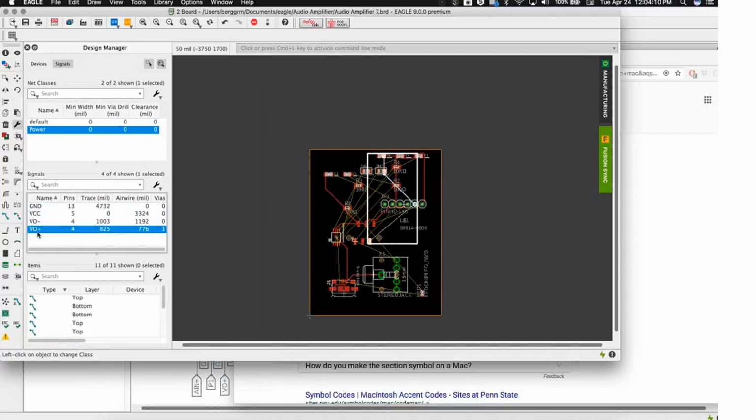So that's a very fundamental interaction in Eagle between the DRC and the net class, and one that some users don't immediately recognize: that they're the same level of constraint. They're just competing with each other on which one is stricter because they're defining minimums. So which one's larger?